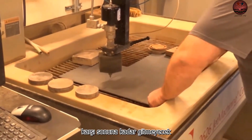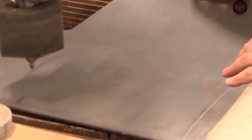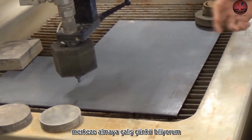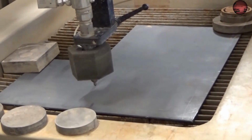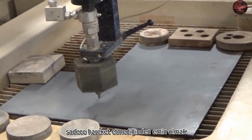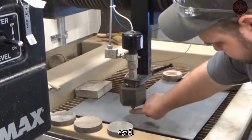Now my head won't actually come all the way up against the edge, so I need to move my part a little bit, or move my material rather. Try to get it centered because I know my head won't come all the way over to the edge. It'll come within a few inches. Making sure it doesn't move. So I want to jog this head down to here.